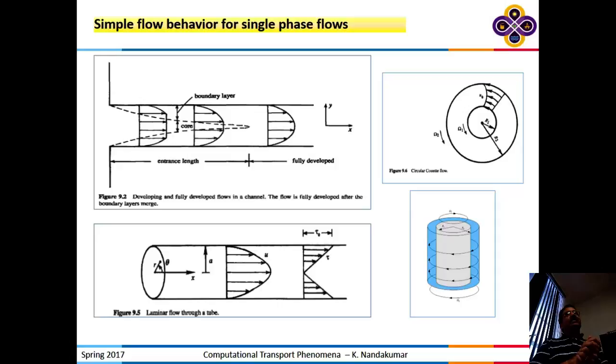I think you said the same thing, I think. For momentum, the higher viscous term you have in honey would dissipate or kind of equilibrate the momentum in a shorter distance. You both are saying the same thing. It sounded like it was different. Is that like whether in honey or water you get a fully developed profile faster? No. The question is, I give you honey and water, you do the experiment, you tell me which one will have a shorter entrance length. Which one will reach the fully developed state quicker along the length?